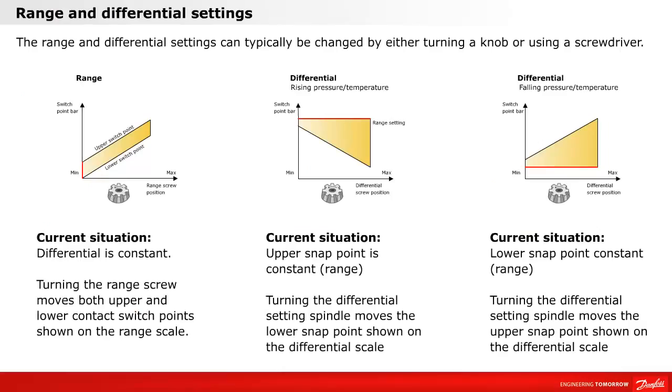The range and differential settings can typically be changed by either turning a knob or using a screwdriver.